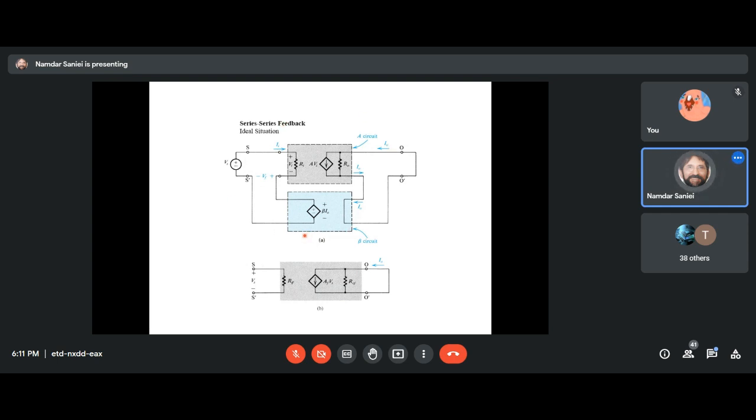The net amplifier with feedback can be modeled like this, with an input resistance under feedback, an output resistance under feedback, and the gain with feedback. Okay, and if you see, it looks the same as the original amplifier that we put under negative feedback. So the formula that we knew works for the gain. The formula that we learned from series shunt, the last case, also works here.